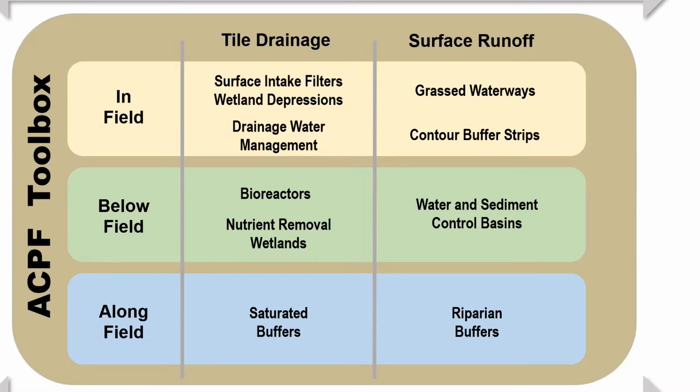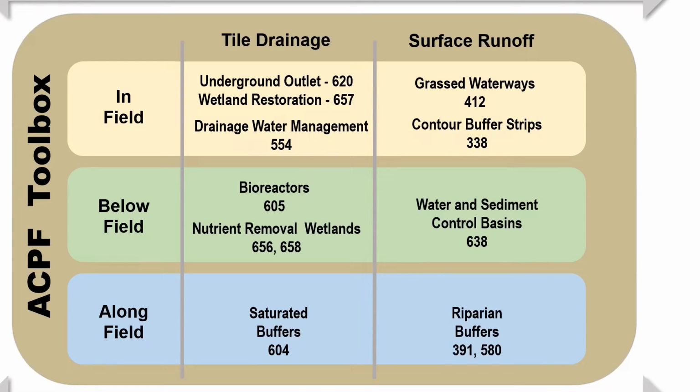Now, these practices are designed to treat tile drainage or surface runoff. As an example, for a below-field surface runoff practice, we will talk about water and sediment control basins, or WASCOBs. An in-field tile drainage practice is what we're going to talk about today, which is drainage water management.